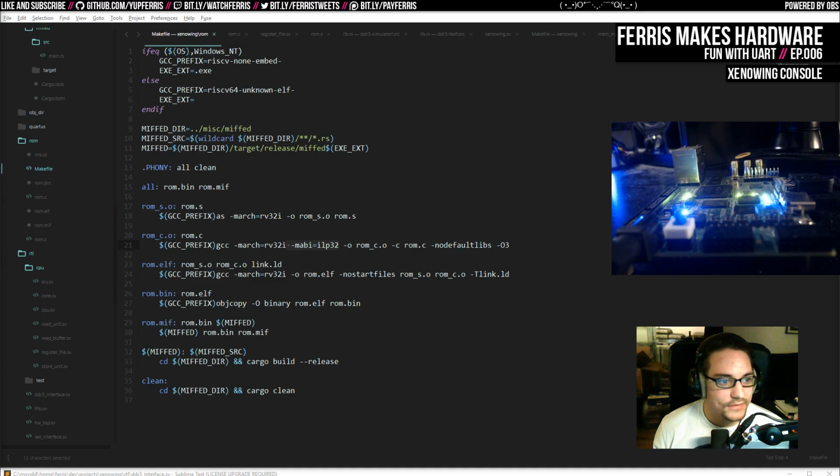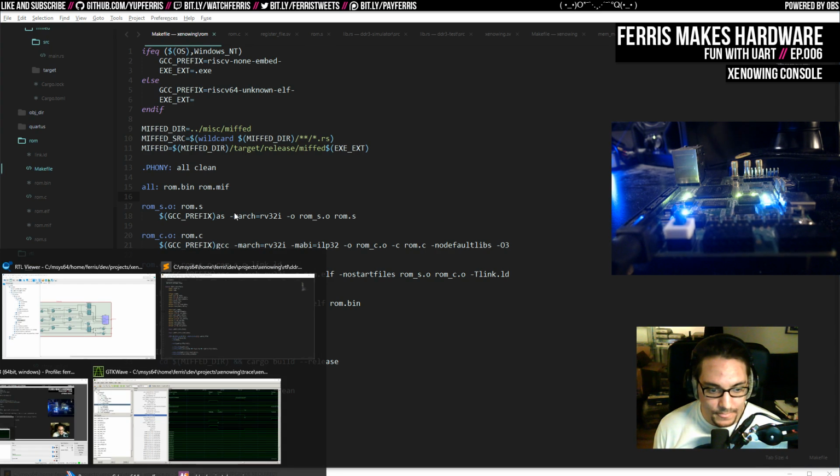And what else did I do? Yeah, so I did that, and then I implemented the UART transmitter. My board has a UART on it. There's two USB ports over here. I don't know if you can see them from that angle. And I can't remember which is which. I think the one on the right is the UART, and the one on the left is the programmer. Anyway, what that gives me is a virtual COM port on my machine. So again, I can pull up PuTTY and just listen to that.